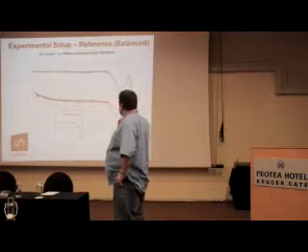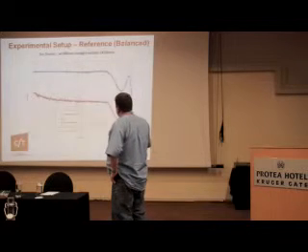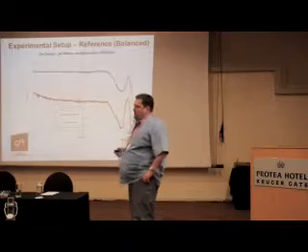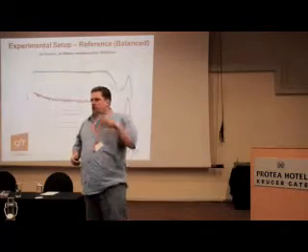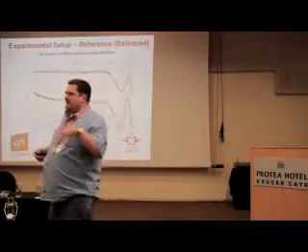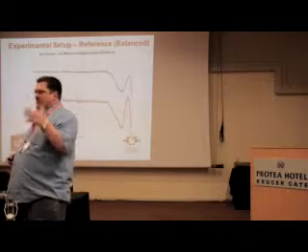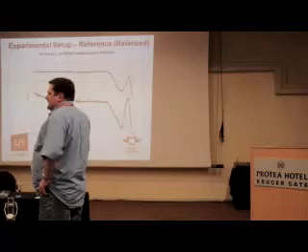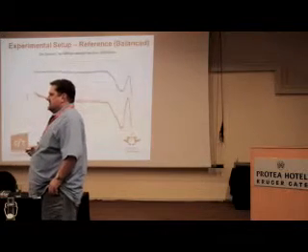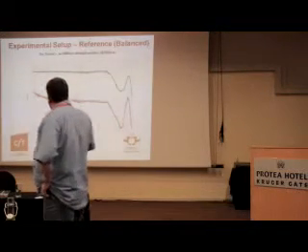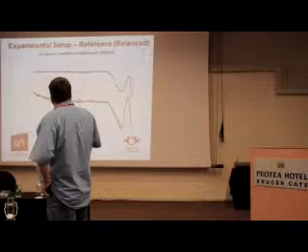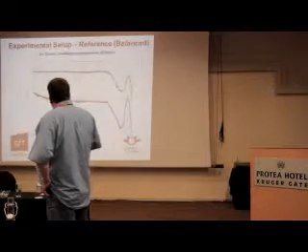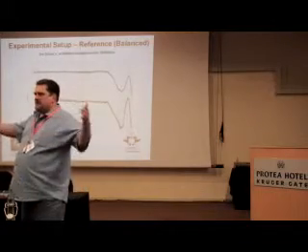In the differential mode, we get a -2 dB drop in the channel, which is normal losses, and it's within the measurement range of our equipment. In the common mode, nothing particularly interesting happens, except that it's very low. And then suddenly something funny happens around 10 megahertz, 20, 30 megahertz for this 2-meter piece of wire.